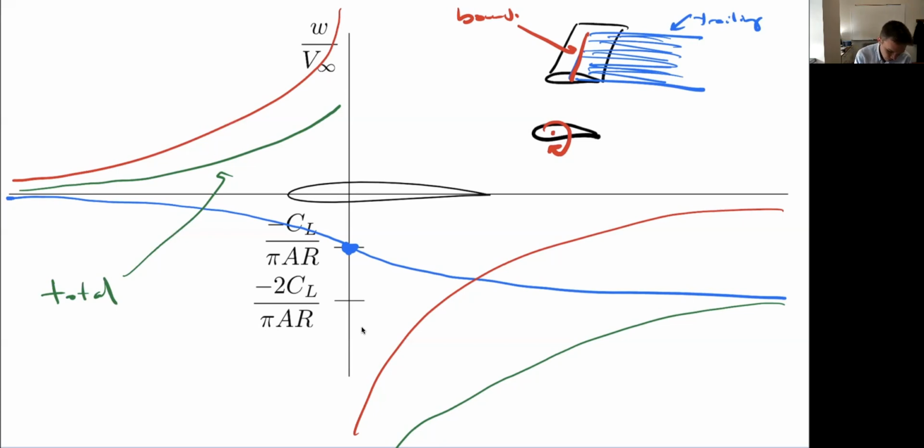And then from Kutta-Joukowski, let's think about the force. So this is a vortex. It's got some strength gamma, and there's some velocity here of this magnitude. So if I take V up, crossed into gamma, so if I curl my fingers around gamma, my thumb is into the page, so that's the direction of gamma. So V up, cross gamma in. This is generating a force, an induced drag, whose magnitude is going to be rho times V times this gamma. So that's going to be gamma 2 over 2 pi r times gamma 1.